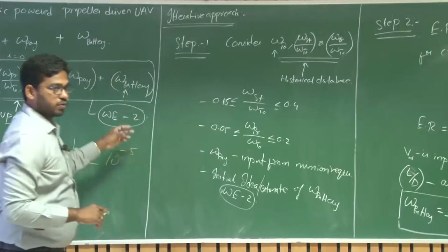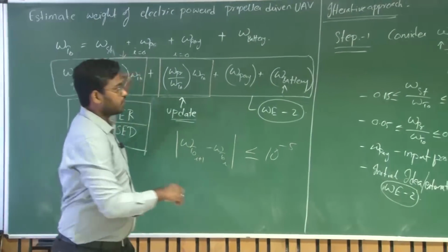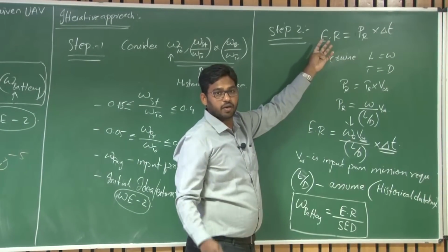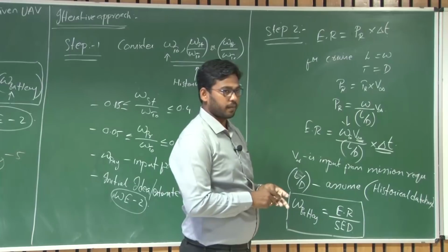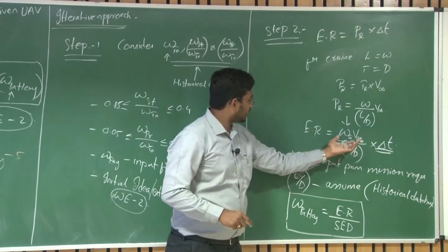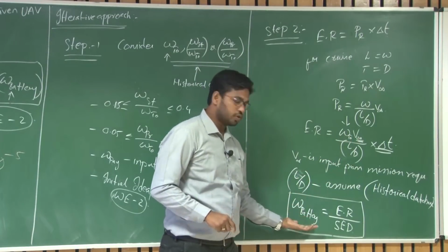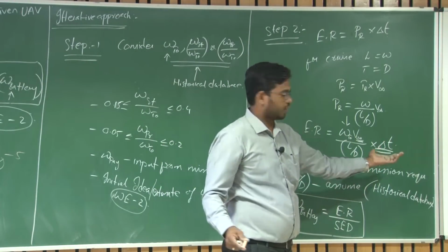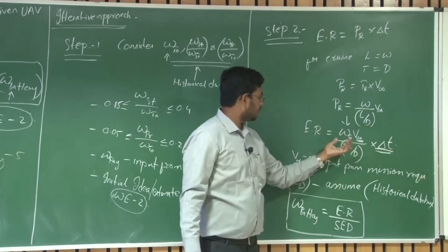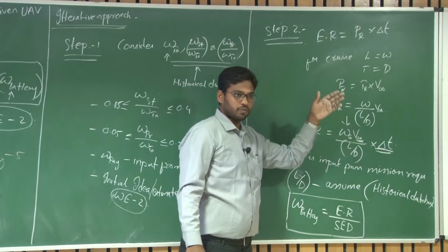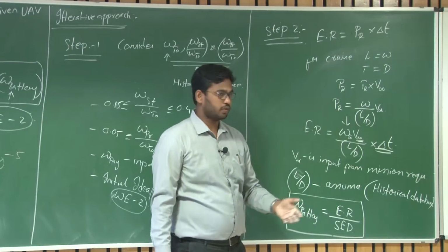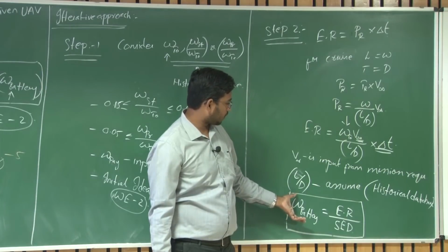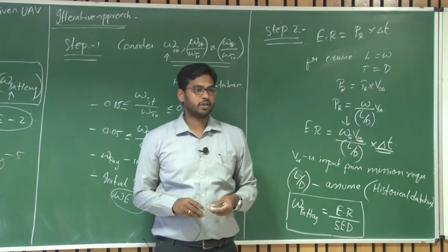So repeat this step. Now since the WTO is changed, again the overall takeoff weight is changed, and the energy requirement to perform this particular mission will change, right? So once you change this, what you have is your new battery weight, assuming the same L by D, and the mission requirement still remains the same. Since the WTO is changed, slowly you are trying to bring it to your current UAV. So your energy requirement also changes.